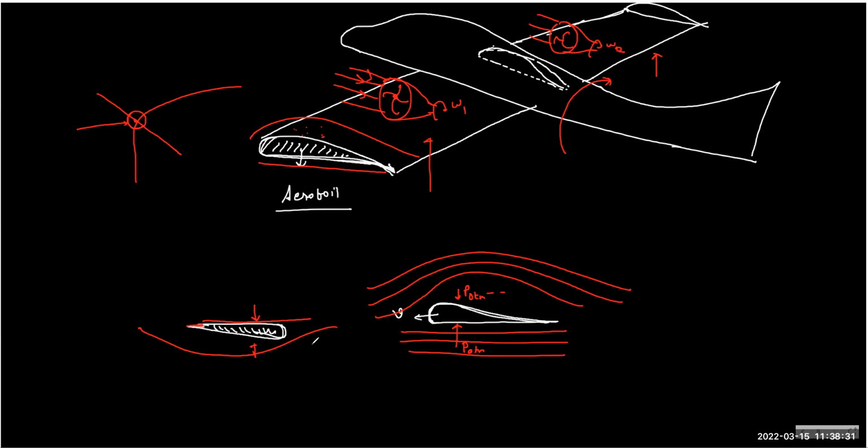The other reason is to minimize the drag also. The spoiler is called spoiler because the spoiler also destroys the streamline near the back, and hence reduces the pressure difference, because when you're cruising through the air, we have air drag acting here also.